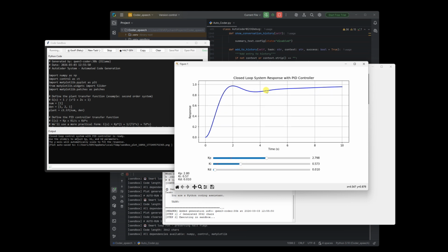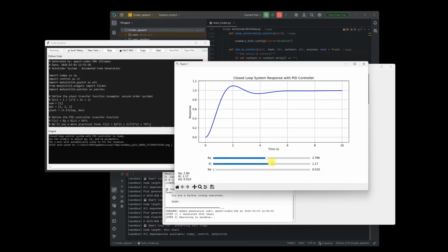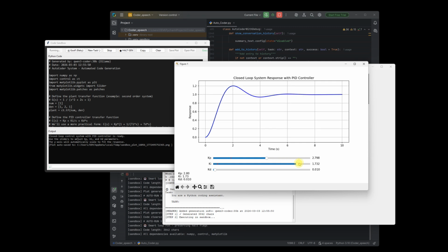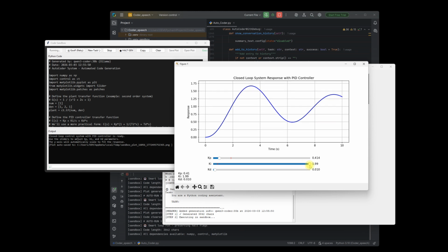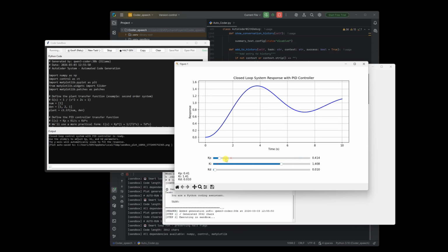And you can see it integrating away the error, and the more integral action I put in, you see the error goes down to 0. It's beautiful, actually, beautiful simulation. And now we're left with all this overshoot. And just to show if I've got integral action on its own, what happens is that I end up with oscillations. Well, it just completely oscillates. And I've had previous videos illustrating this for real systems. This is, of course, a simulation.